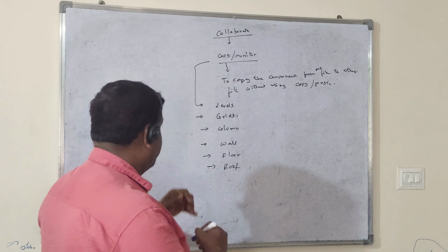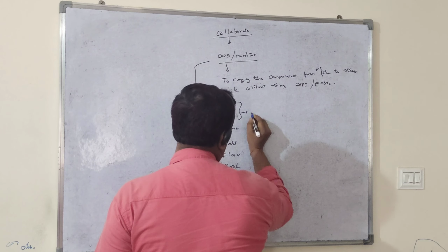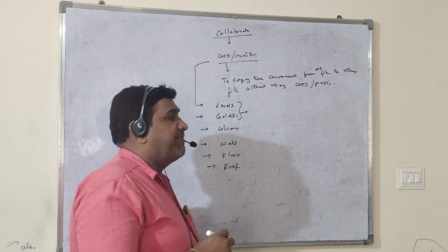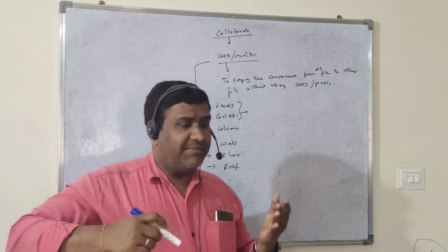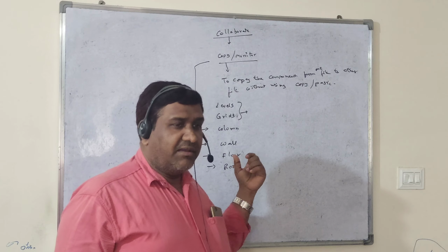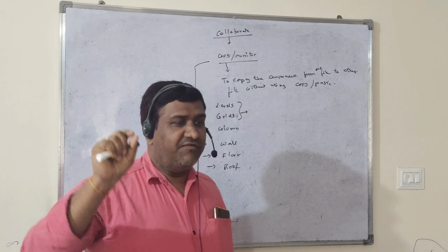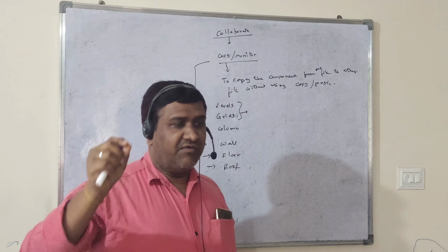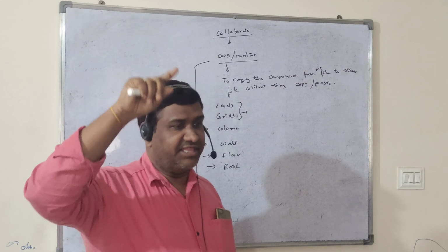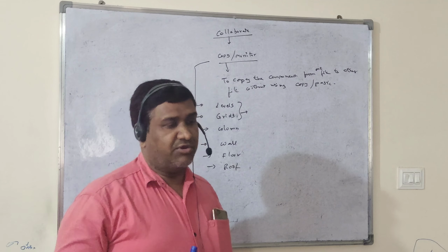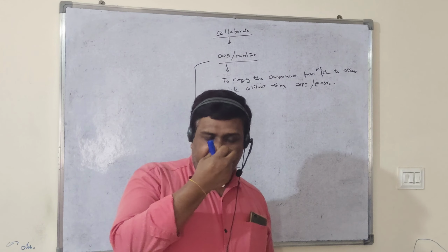Okay, so first we will use it for the levels and grids, because this is very important when you go to any company. Initially you did these levels and grids manually, am I right? Manually, by seeing the AutoCAD, what the levels of the floors are, you made the number of levels, then you placed the grids as per the location of the project. Okay, manually you did it.